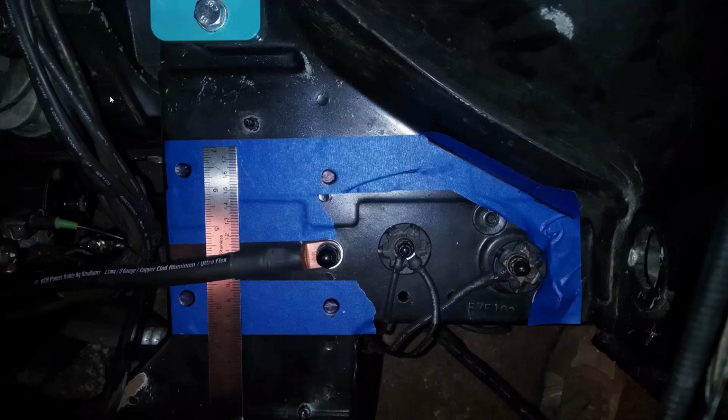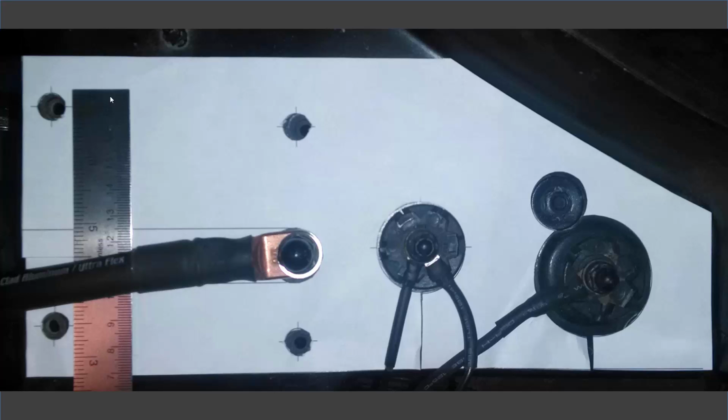And I had that here, and that's the reason why I did a two-step process. So I fed this image into SolidWorks. I created a very basic 2D shape, and then I took that 2D shape into a SolidWorks drawing, scaled 1:1, printed it out on my printer, and then cut it out, and I end up with this. So now you're looking at a version 2 of the template.